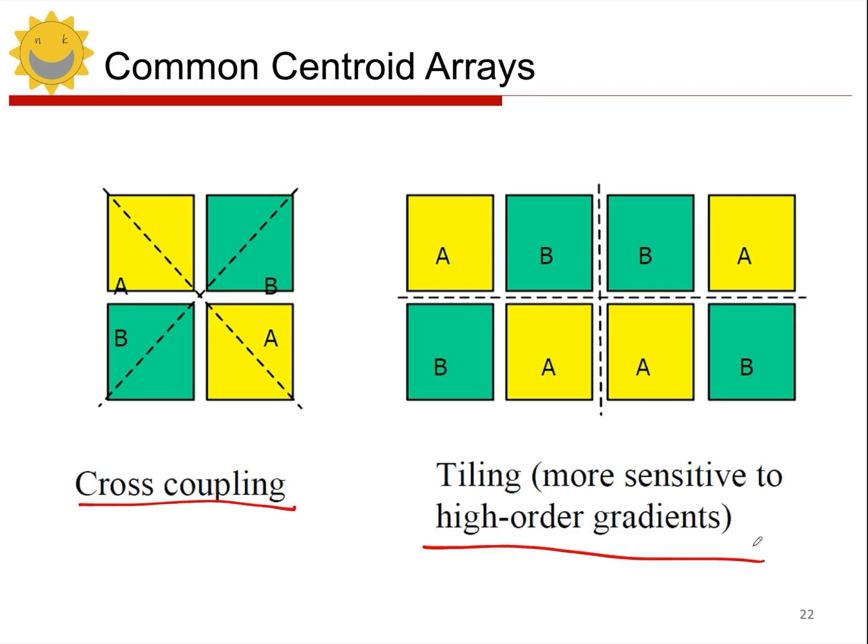So if we decompose them even more, we can arrange them like this, right? This is AB, and then we have ABA, and then BAB. So on the left, we have a square cross layout of ABA, and on the right, we can do it again, creating a mirrored version. Right, in this way the centroids of A and B will both fall on this node. They will land here, which makes it more consistent, right? More consistent.